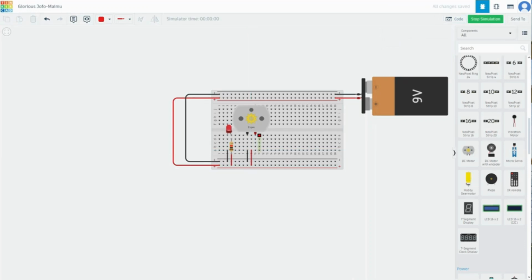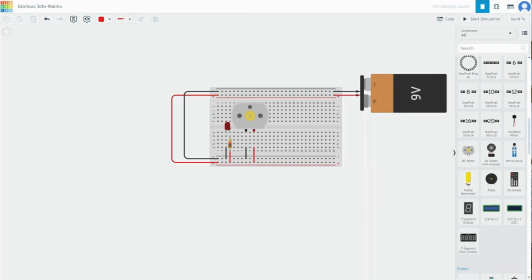And if I start the simulation, for some reason you can see it isn't running. Now, that's because motors actually have a 3 wide gap. It's like 3 dots. So you actually have to move this over by 1. Unlike LEDs or bulbs where the points are next to each other, this one's a bit far apart. So now if I start the simulation, it turns on, and with the 9 volts, this DC motor runs at 17,548 rounds per minute.